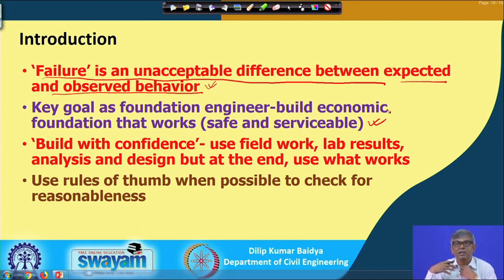That means, if the design comes 1 meter, but I adopt something 1.5 meter, there may be some insight I have that 1 meter may not work, though the design is giving 1 meter. Still I will adopt 1.5 meter or 1.25 meter; my insight actually will not permit 1 meter. With experience you will gain this. Key goal as a foundation engineer: build economic foundation that works, that means safe and serviceable.